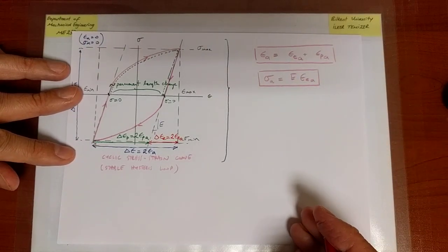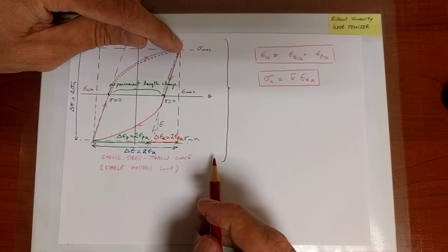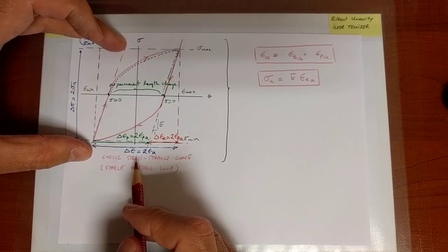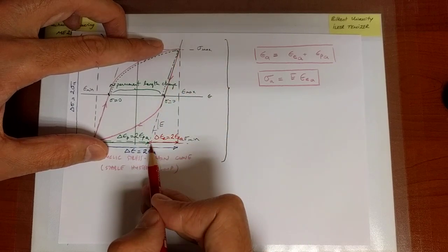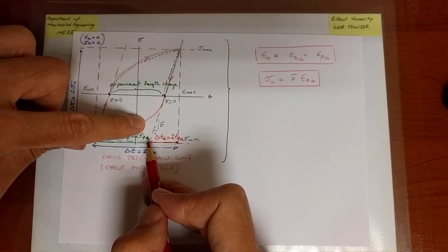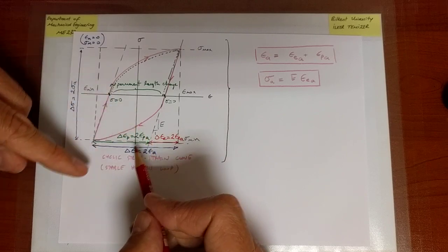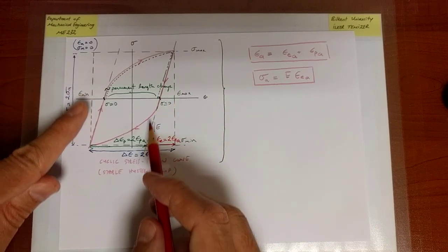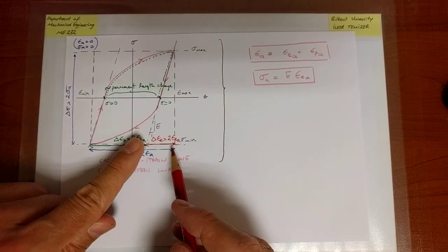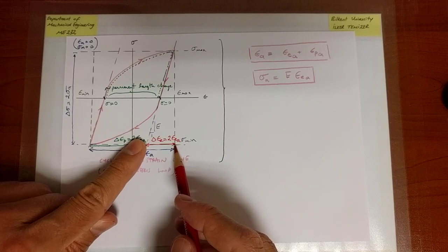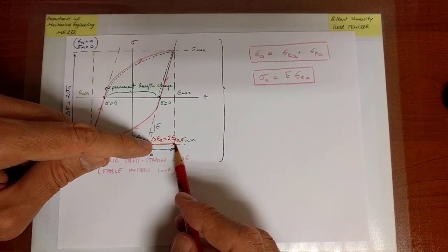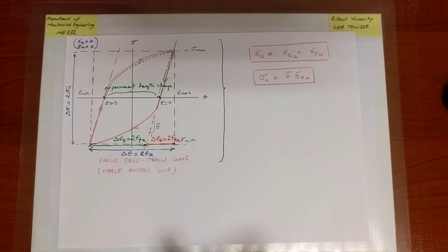which is again comforting because it correlates with our earlier discussion, which says that unloading is elastic. That's exactly what we're seeing here, except that a portion of unloading is on one side, the other portion of unloading is on the other side. So the triangle itself is not lying along an elastic unloading, but eventually when we overall look at the deformation and judge that this is the total strain, this portion of it is indeed associated with pure plastic deformation, and hence this must be pure elastic deformation. From that, we also again calculate that the stress change is associated with strain change through a linear relation where the proportionality constant is the Young's modulus. So it's again exactly the same thing.